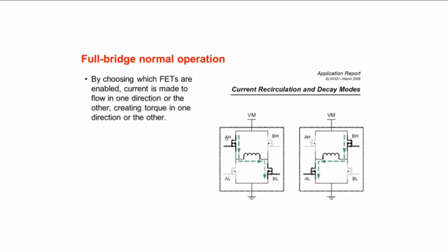Historically these have often been relays, on off, on off. But if we want a full bridge with intelligence and better control, we are typically going to replace relays with transistors of some type, typically a power MOSFET, depending on the size of the motor. So we see a forward direction.